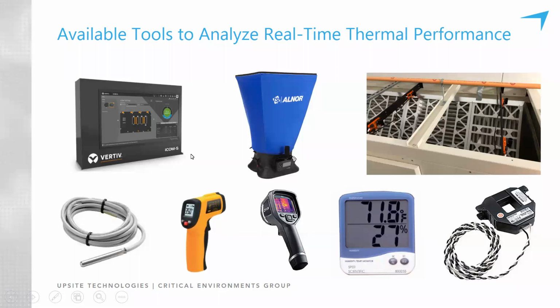kind of a team. Next, you've got your basic flow hood or anemometer that are commonly used to measure flow and capture other airflow metrics at the floor tile or at the ceiling register. Those are used throughout the data centers on a one-by-one basis or in contained aisles. You've got mass airflow sensors that are placed in the return air stream of AC units to help measure enthalpy.